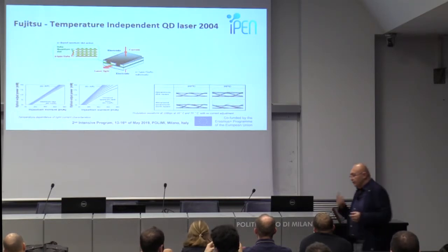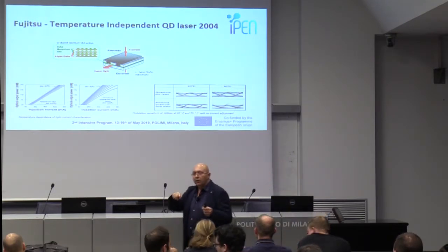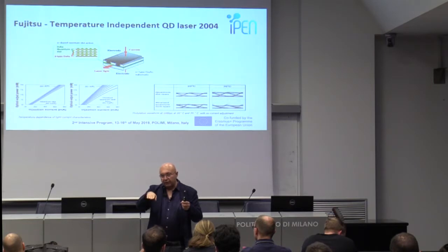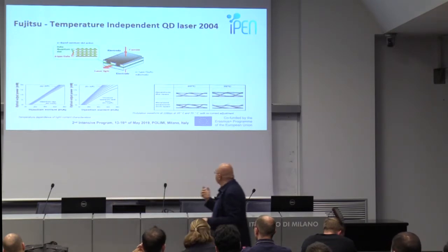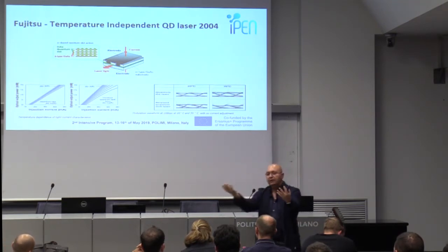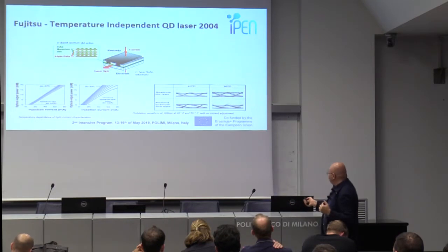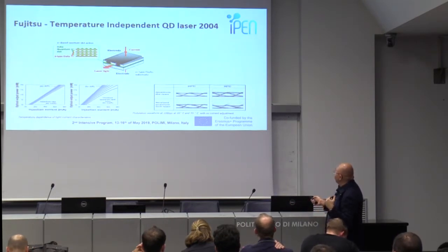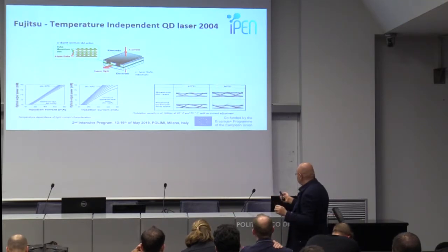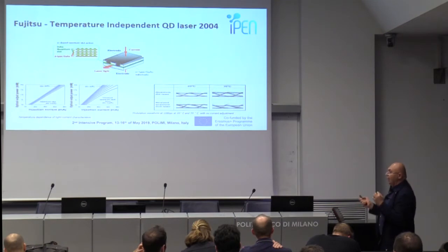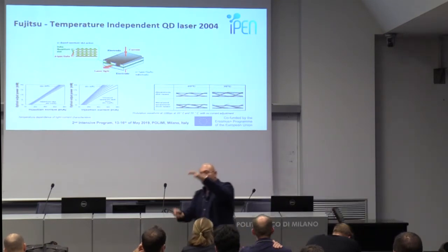No? So actually, when you are transmitting so-called on-off keying, it is the modulation form where you transmit 0 for a low optical level and 1 for a high optical level. In this way, you can transmit information. To check the performance of the system, you just accumulate these symbols. If there is noise or the dynamical properties of the device are poor, this eye will be very closed. So if the eye is open, the situation is good. If the eye is closed, that means we have a lot of noise.